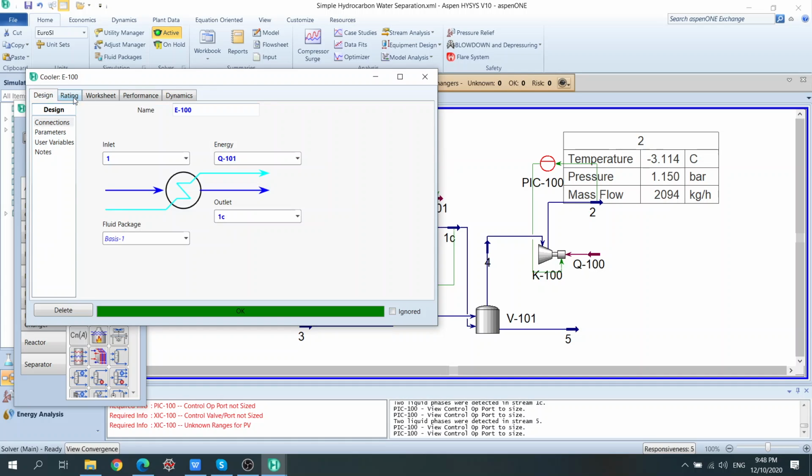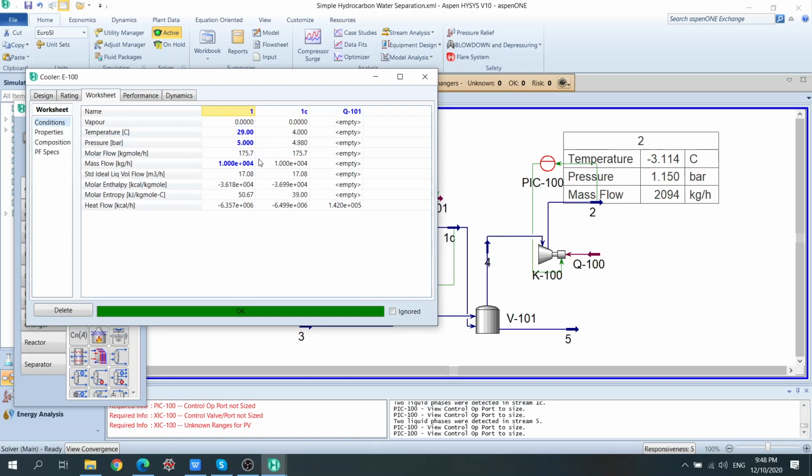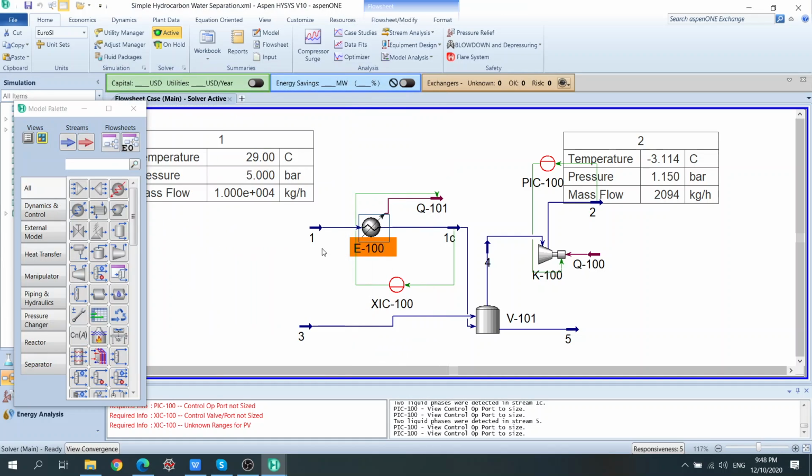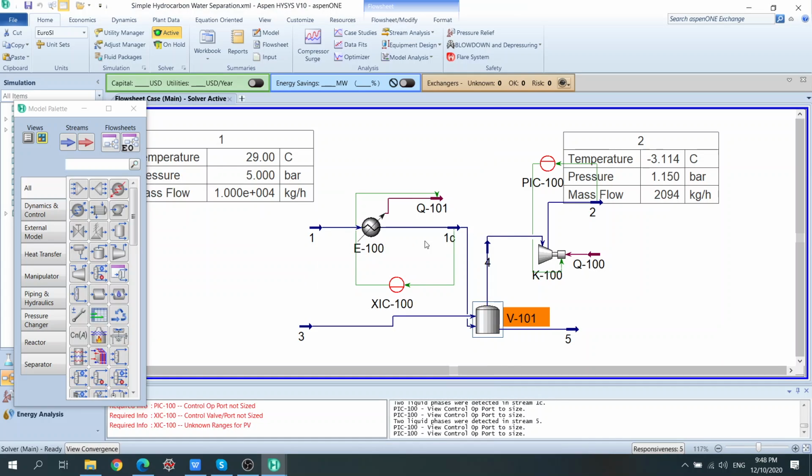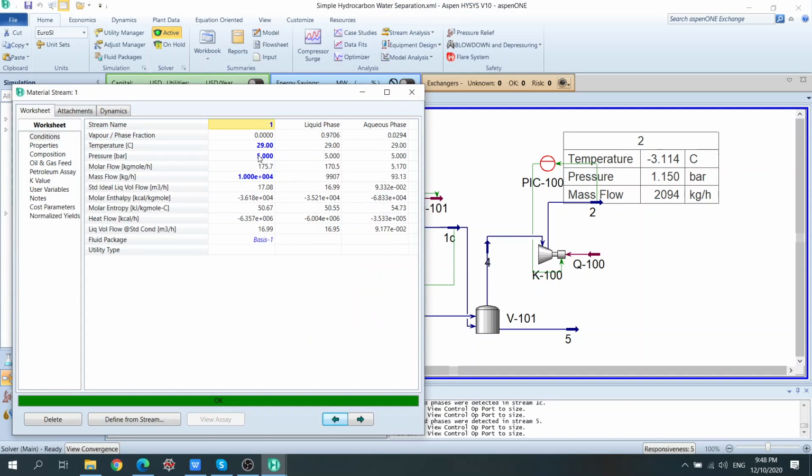Yeah, you put the pressure too low, because it won't be good for dynamic. At least we need to have some pressure drop around the system. If this is 1 and then there's 0.8, this has to be lower than 0.8. If this is at higher pressure, there won't be any flow coming from this side. So we need to increase this to maybe 4.